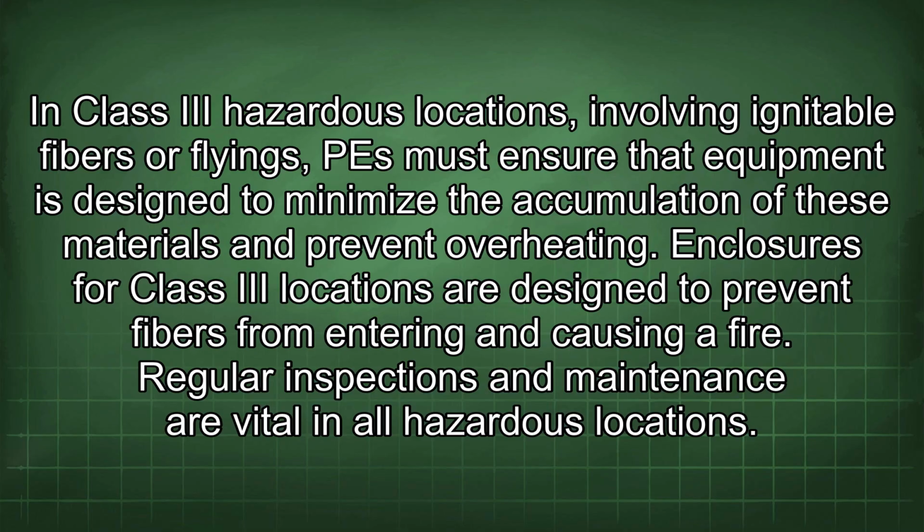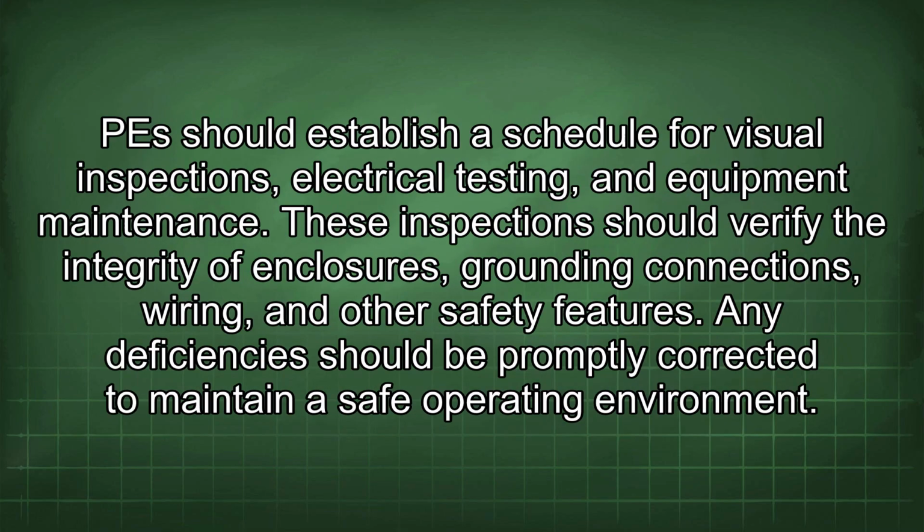Regular inspections and maintenance are vital in all hazardous locations. PE should establish a schedule for visual inspections, electrical testing, and equipment maintenance. These inspections should verify the integrity of enclosures, grounding connections, wiring, and other safety features. Any deficiencies should be promptly corrected to maintain a safe operating environment.